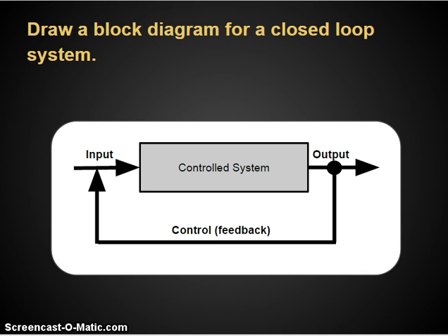Now the feedback loop often takes the form of some form of electronic sensor. If we're going back to the robotics example, it would be like an encoder on one of the wheels. An encoder is something that measures rotational speed. You have the encoders attached to the wheels. That way, if they're driving and one motor is underperforming, like I gave you in the example, the feedback loop from the encoder will tell the main computer, okay, this motor isn't spinning as fast as the other motor, so it can slow down the other motor to match speeds, so that way it'll drive in a straight line.